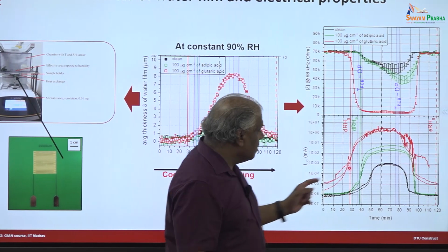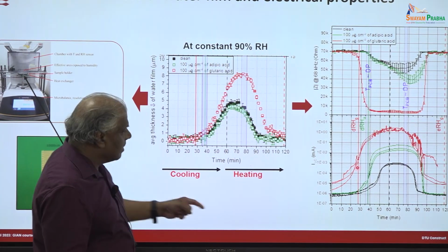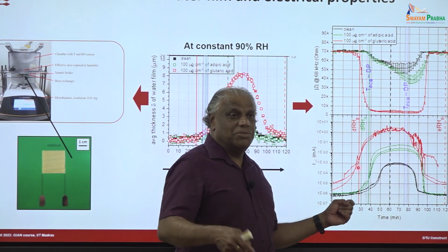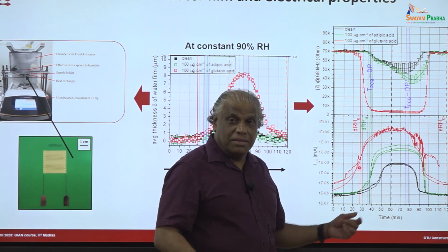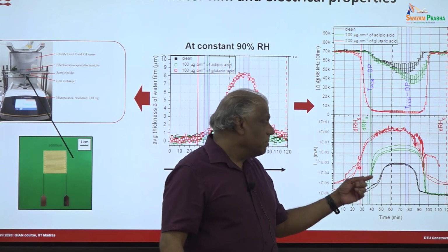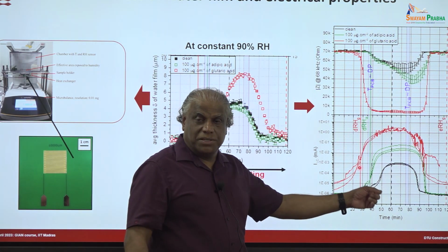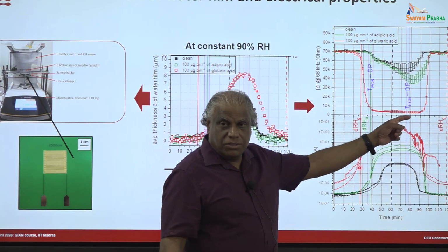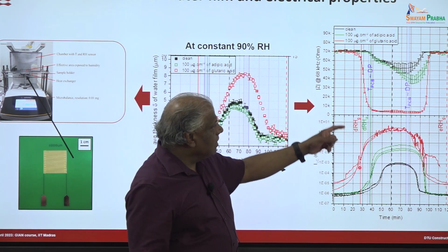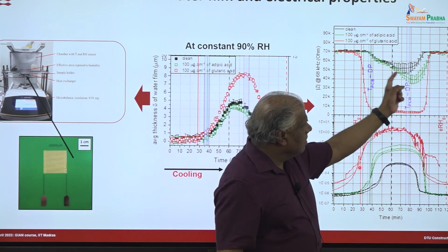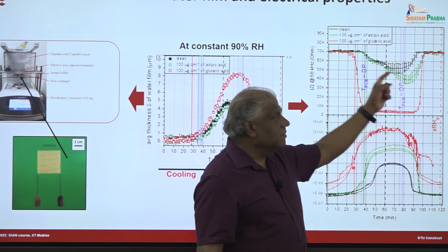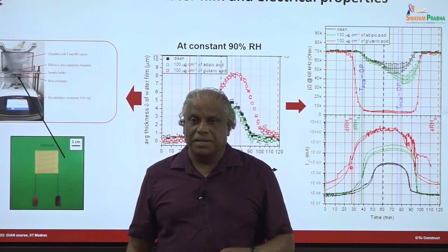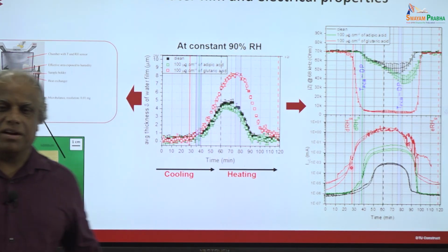So you can see that for each water film thickness, we can get the electrical property. How can I use this? You will see later that we make the electrochemical model, and we can calibrate that model with these values, because we know the electrical property, not just leak current, but also correspondingly the impedance. Impedance shows a similar thing: with the clean PCB, adipic acid and glutaric acid, the impedance dropped, so it corresponds to this one. So we have the full calibration of that water film thickness.